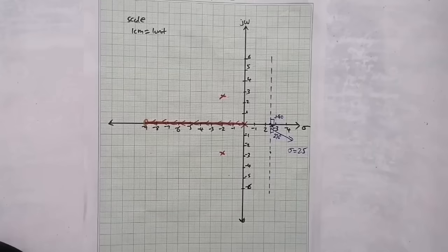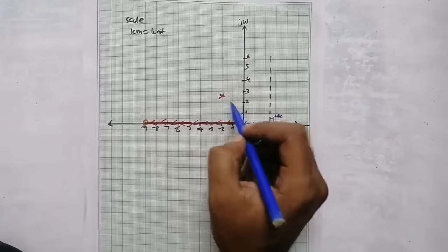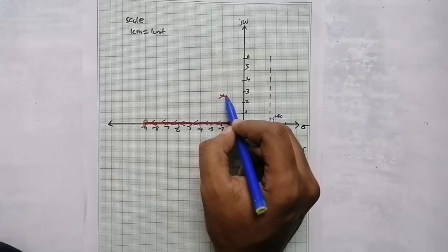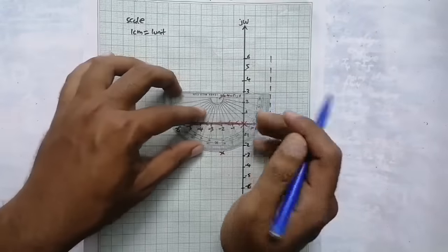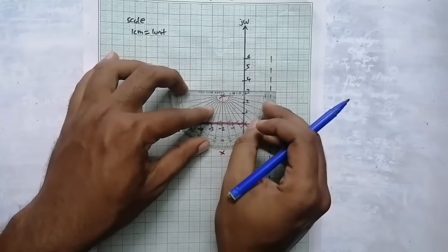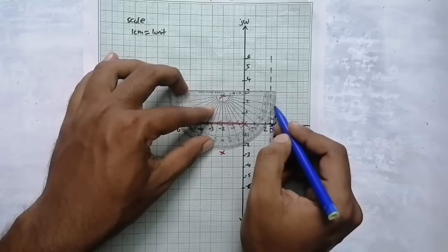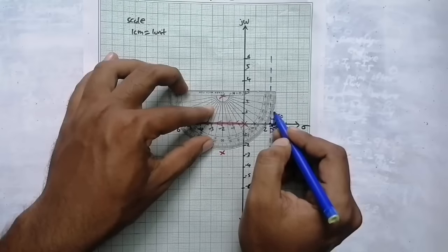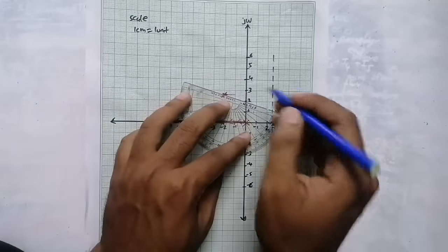Now for drawing the angle of departure we took the first complex pole. So first of all draw a straight line. This is the baseline for keeping the protractor. Then keep the protractor there. Then you need to take what angle? Minus 70 degrees. 0, 10, 15 and here it is 70. So draw a straight line. This is the reference line for drawing.